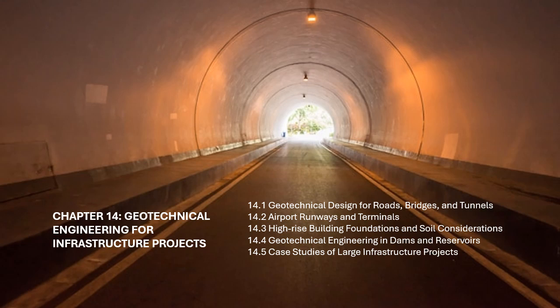Tunnel lining design. Tunnel linings are designed to support the tunnel structure and prevent collapse during excavation. The lining must be designed to withstand the stresses generated by the surrounding soil and rock, groundwater pressure, and potential seismic forces. Common tunnel lining materials include concrete, steel, and shotcrete.